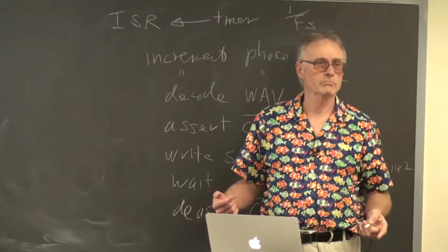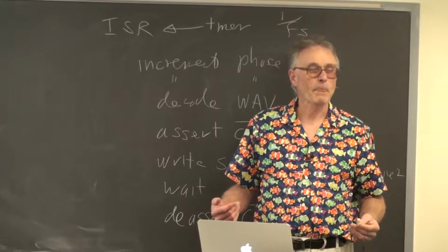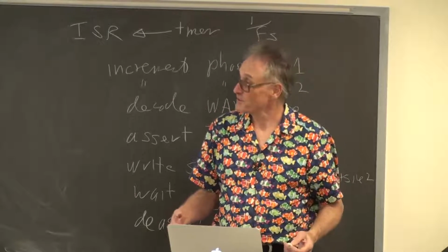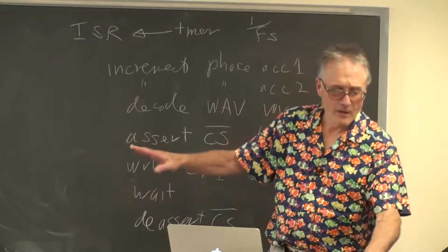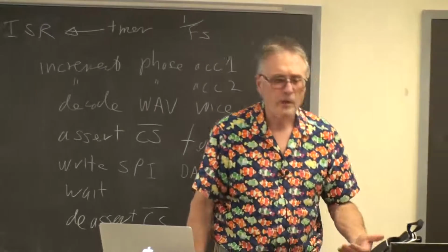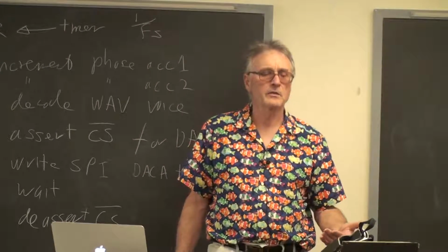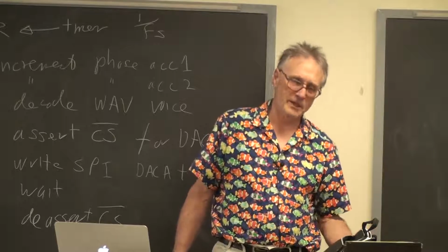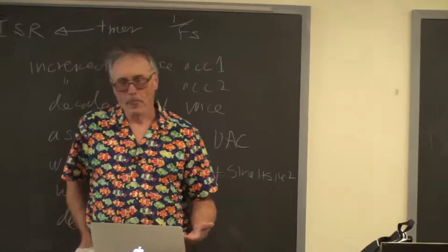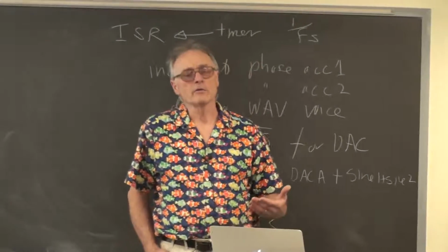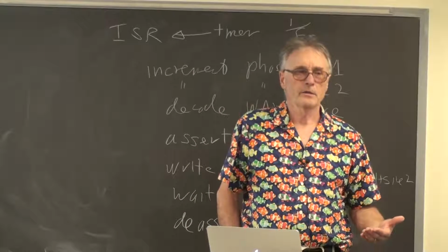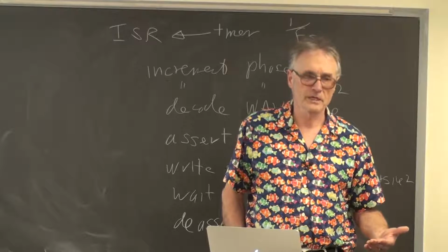You talked about doing this without the CPU involved at all. Can you talk about that again? Yes. Sean, would you like to talk about that? Yeah. Hold on. So it is possible to drive an SPI channel using the direct memory access device. There is a mode called a framed transfer on the SPI that allows you to use a direct memory access channel to spit out data to an SPI endpoint.